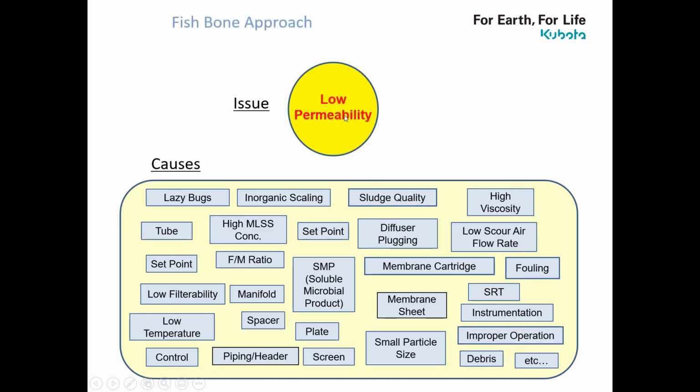But low permeability can be caused from all different kinds of things. It could be a membrane issue, it could be set point issues, it could be some instrumentation issues. So there could be a lot of reasons.